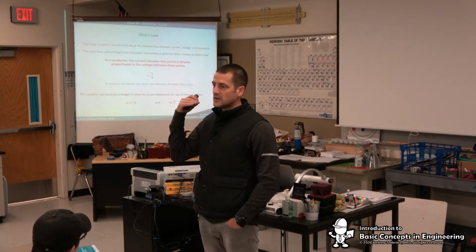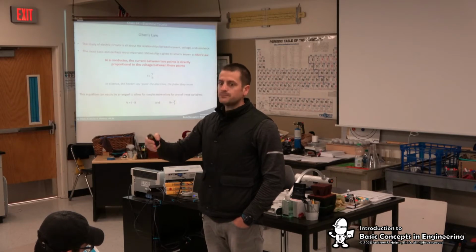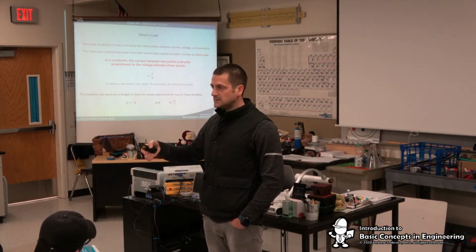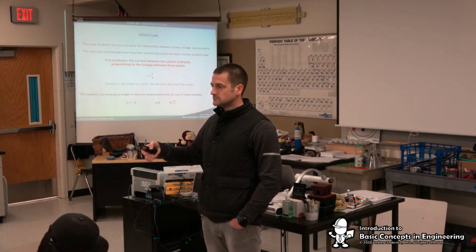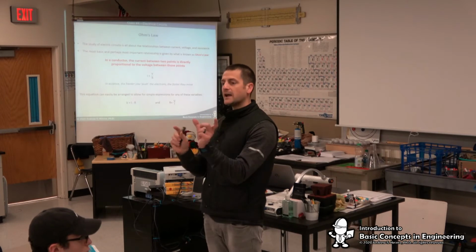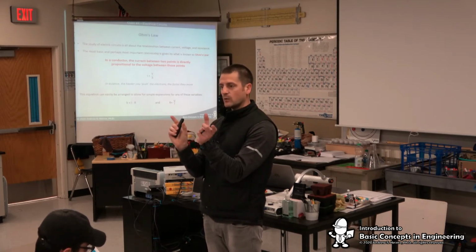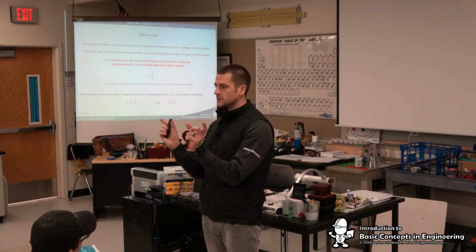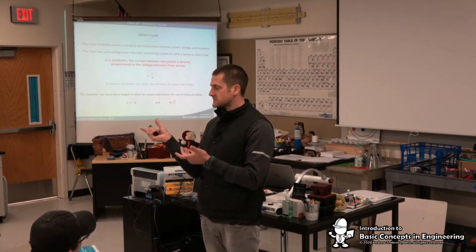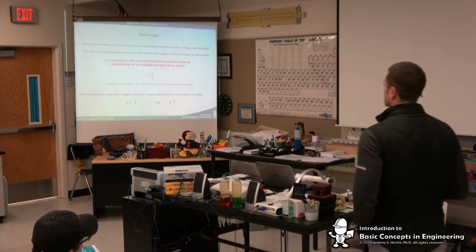If I apply the same volts to a higher R, what has to happen to my I? Let's think about it this way. IR equals IR, same voltage, so let's put the two equations together. I1 R1 equals I2 R2. If R2 is larger, what does I2 have to be? It has to be smaller, otherwise they wouldn't balance out, right? It's just proportions, okay? Very good, guys.